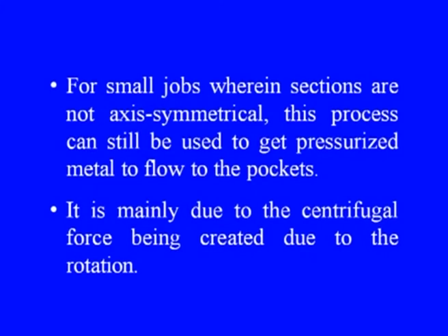For small jobs wherein sections are non-axisymmetrical, this process can still be used to get pressurized metal to flow to the pockets. It is mainly due to the centrifugal force being created due to the rotation. If the masses are properly balanced, then we can have uniform layers stacked one over the other.